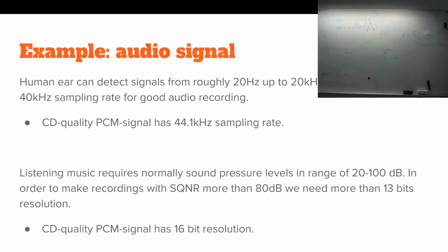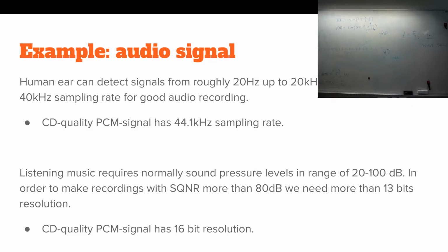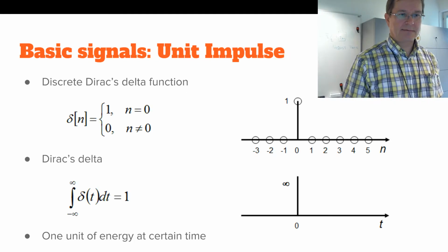So basically you need to get rid of all the electromagnetic interference at higher frequencies. Okay, so a 44.1 kilohertz sampling rate would give you a reasonable area that you can do with high precision and with low noise. Okay, nice. Now you know.